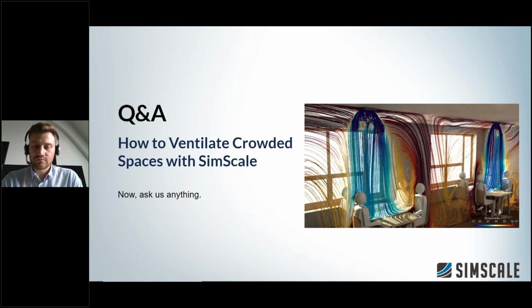So Jeremy and the other attendees, we'll send a link to the solar webinar recording, and in that we demo the new features, how to set up solar gain in more detail using climate data, or just entering latitude, longitude, and then it talks you through the different aspects of the solar gain, how it enters the space, how it distributes in the room, and how to post-process and visualize that solar gain as well, and how to extract that in your results. So that's a great question, Jeremy. Thank you, and we'll follow up with further information on that.